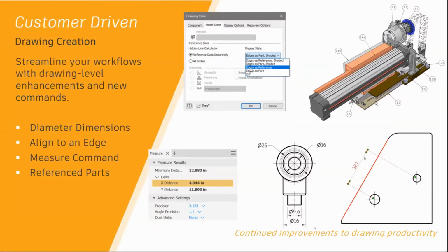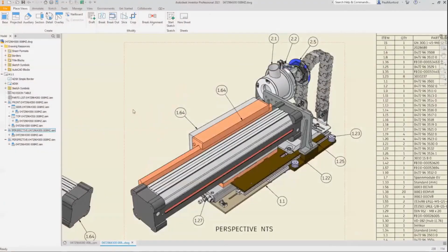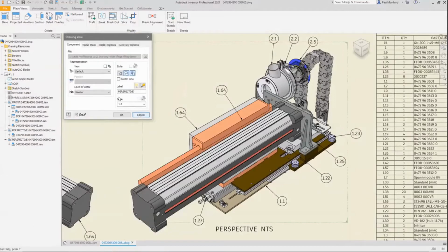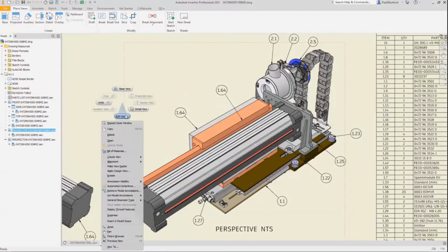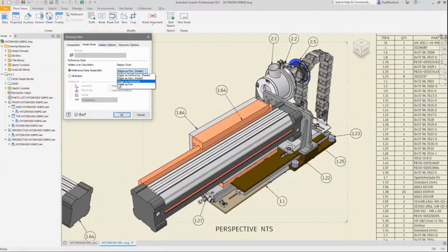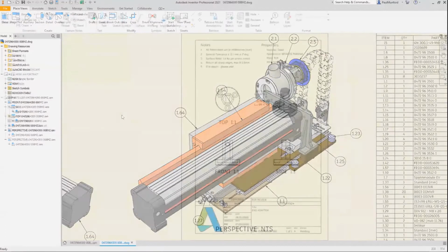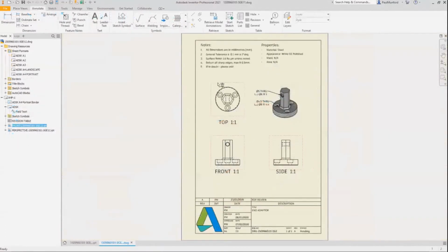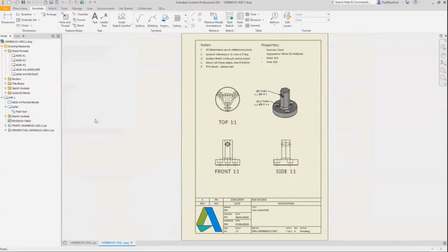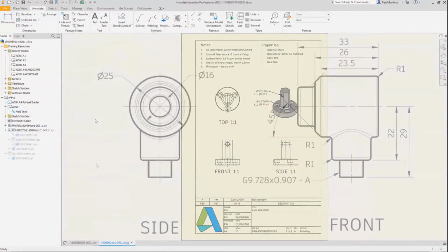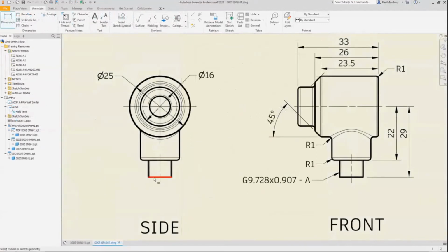So you can also now create a shaded look for your reference parts. So if you're referencing a part, you can now view them as dashed lines. So components set to reference in the Inventor bill of materials have a new visibility option in drawings, which is the reference files in colors, so with or without dashed lines. So the ability to add automated center lines to drawing views has been made easier to discover with a new button for the automated center line command in the ribbon.